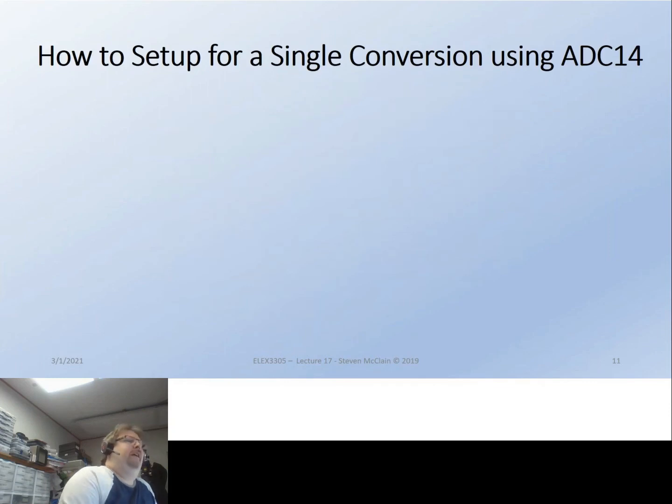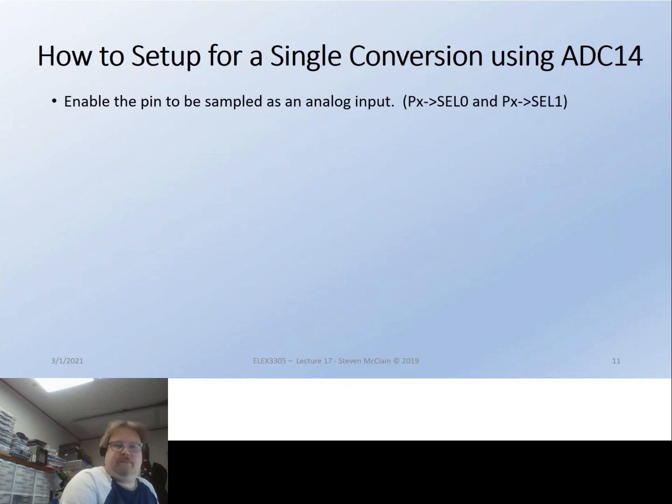Okay. How to set up for single conversion. Now we're getting to some meat here. Sorry for taking too much time here, but this is hopefully clearing some stuff up for you. You got to do the SEL stuff. Remember SEL, how that worked? Because we're not using those pins as general purpose input outputs anymore. Now we want to have them hooked up to their internal function. So we got to program those the right way.